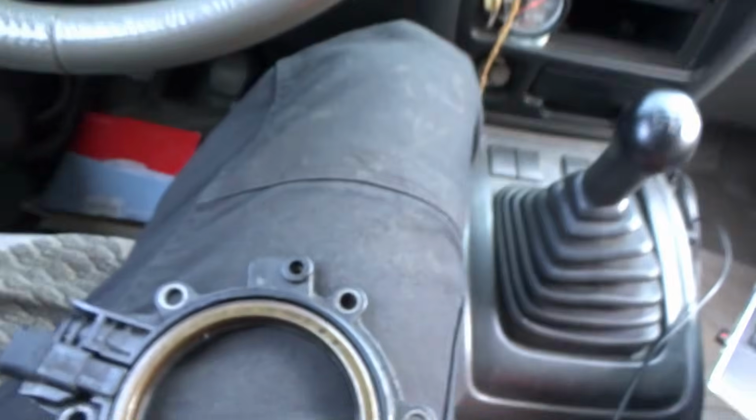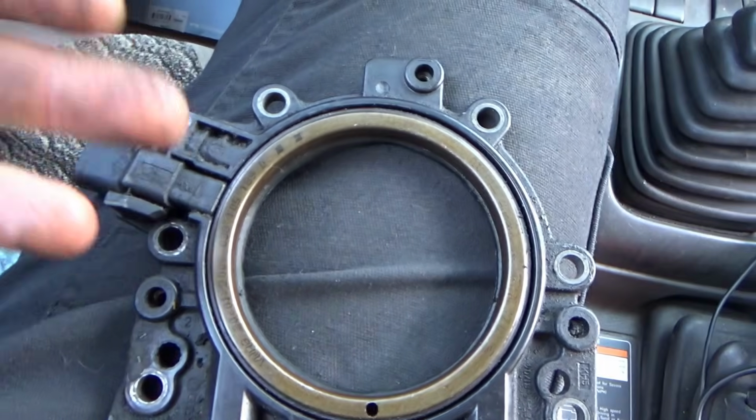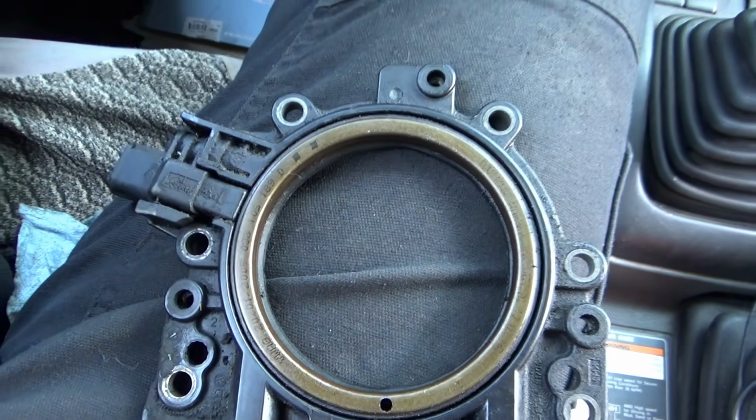But regardless, if you just press this on wherever the engine's at, your timing of the crank pulses are just going to be random. They're going to be off. That's the entire problem with this Volkswagen. The rear main seal was installed improperly. It wasn't timed correctly to the crankshaft. Mind completely blown. We've been here over 6 hours. I've been on the phone for almost an hour.